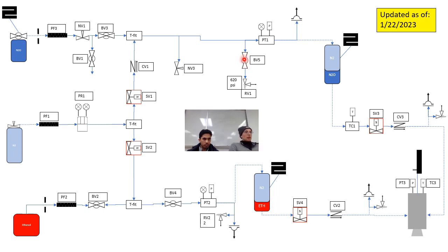We also at that point enable bang or closed loop control of the nitrous oxide pressure. It is critical that we keep that nitrous oxide pressure at 620 or 600. We want it to be above really like 580. I'm just saying this range of values, nothing is set in stone. We definitely want to keep it above 540, and our goal is like 600 plus or minus 20.